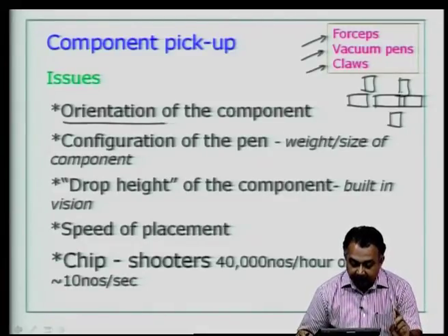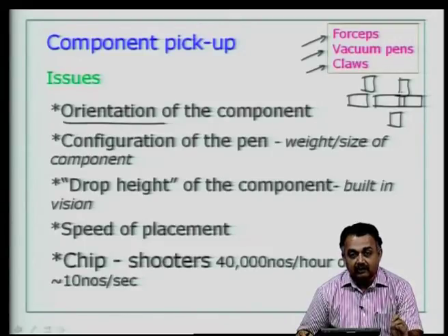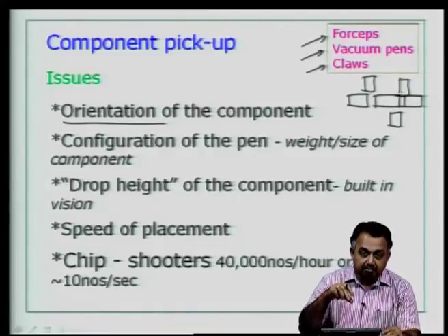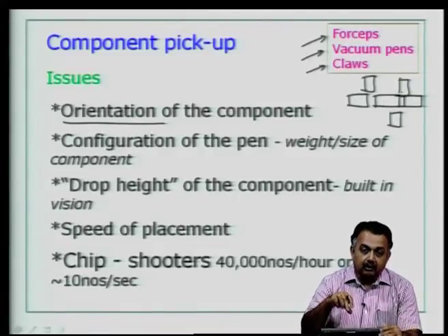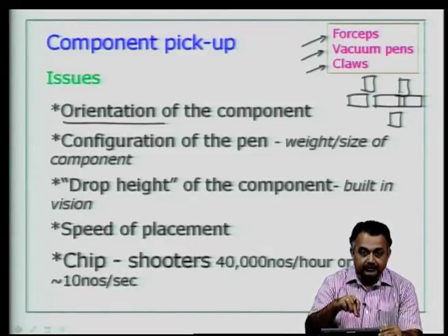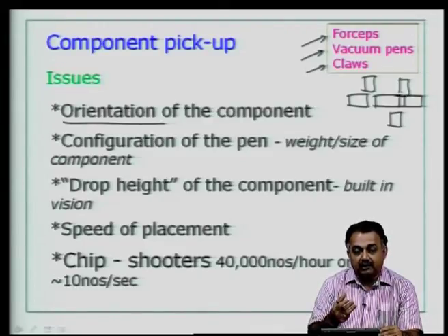The configuration of the pen is very important, weight and size of the component. The drop height of the component is an important issue as far as the equipment is concerned. Typically, the equipment does not place by moving the component to its right coordinates on the board. It typically drops at a certain height away from the board, and a solder paste material in the case of reflow soldering has to get the component attached to itself.